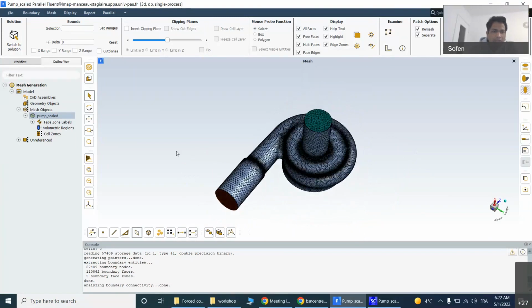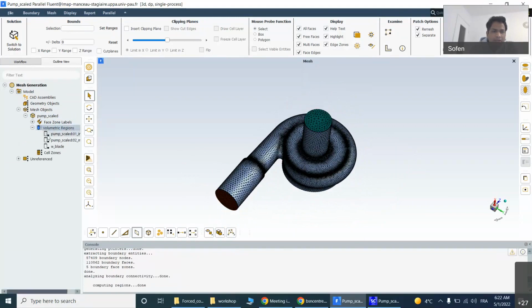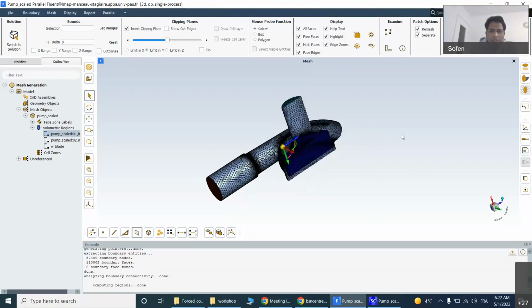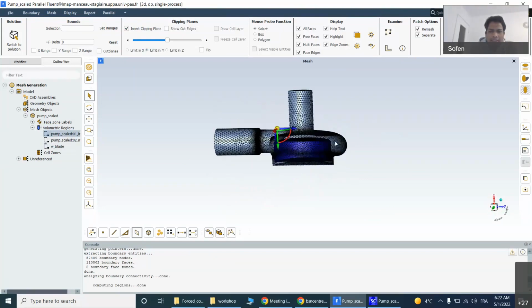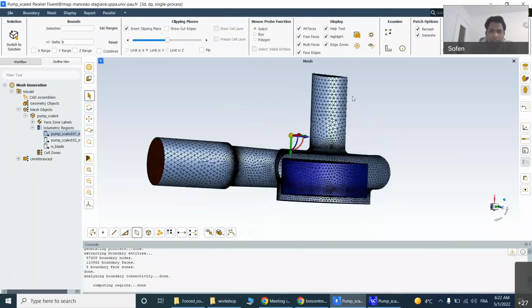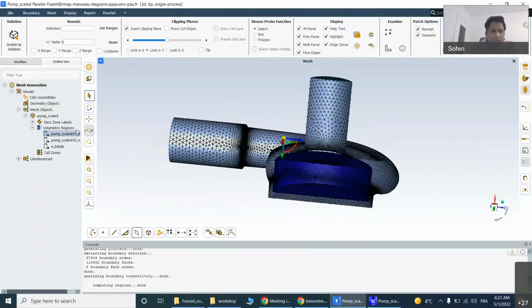Okay. So let's compute the volumetric region. We computed the volumetric region. How many volumetric regions were prepared? Three volumetric regions were prepared, right? So let's see what those volumetric regions are. Okay, reset the view. Let's see what the first one is. This one is showing the casing and the fluid domain where we are solving only the Navier-Stokes equation. We can name it something here.